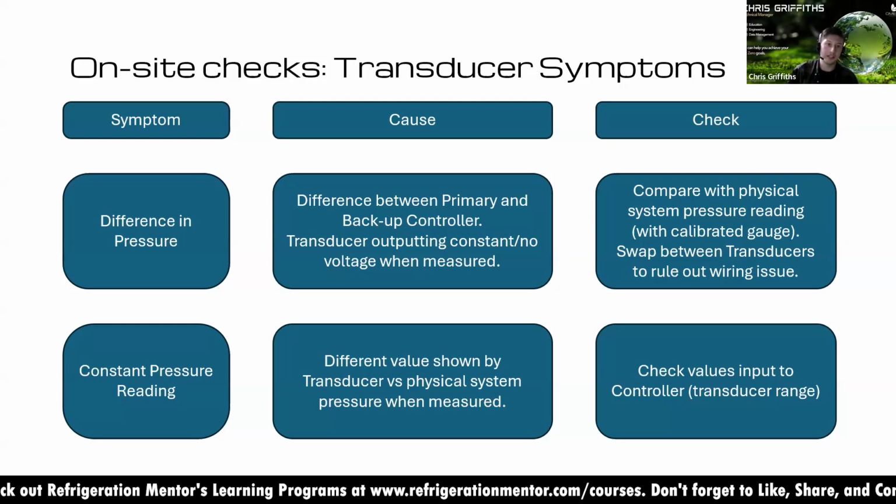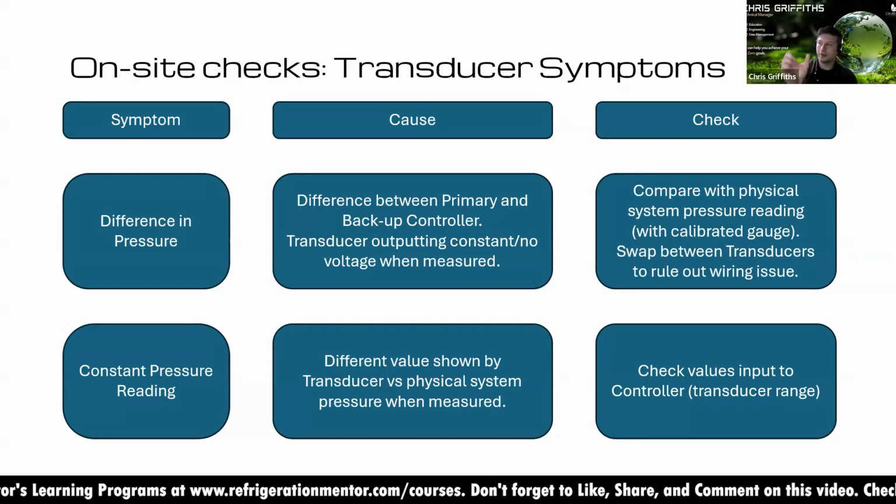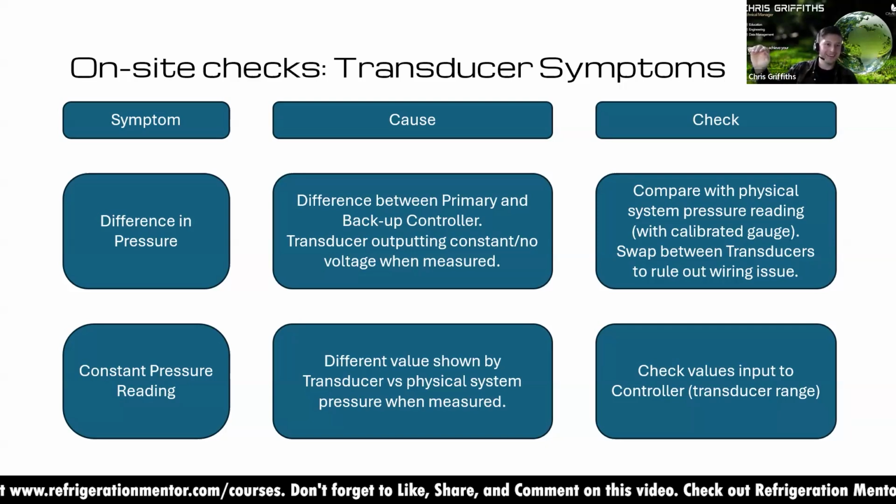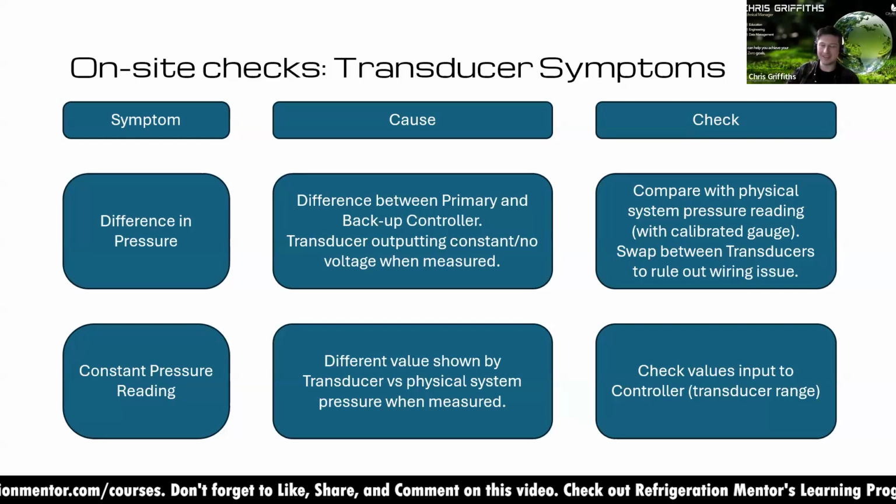So again, it goes back to commissioning checks. Make sure that transducer is actually reading what it should be. You'd think it would occur to you when it's a consistent 28 bar at all times for a week, that the system's working really well. Consistent suction pressure. No, it's because it's not reading correctly. So that's one of the things we can check if it's a transducer.